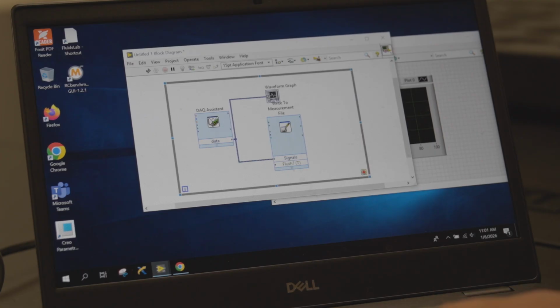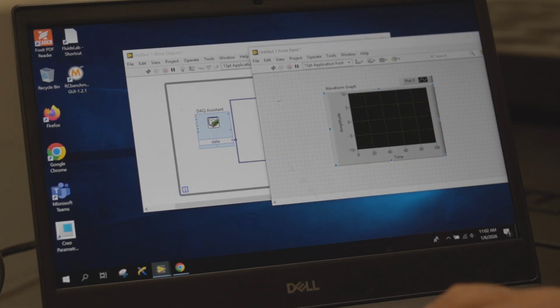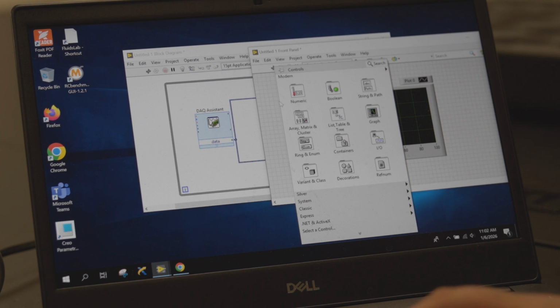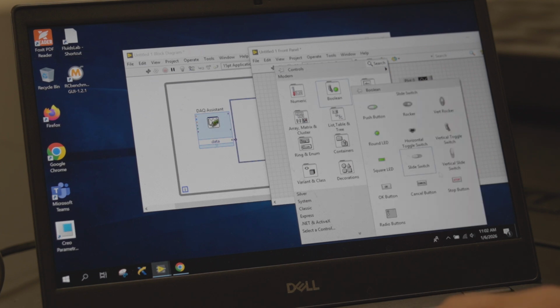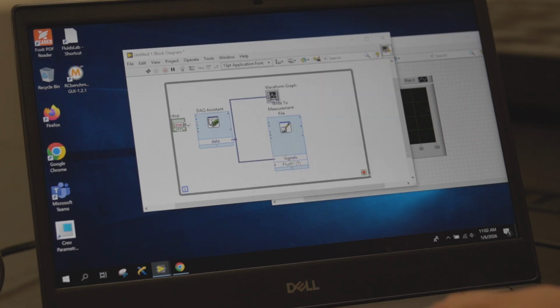And we are going to need to have a loop condition. The loop condition that we are going to assign is essentially just a stop button on the front panel, right? You right-click on the front panel, and you go to Boolean. It gives you a stop button. I'm going to place the stop button right here, and then I'm going to connect. Let me actually move this closer to the loop condition. I'm going to connect my stop button to the loop end condition.